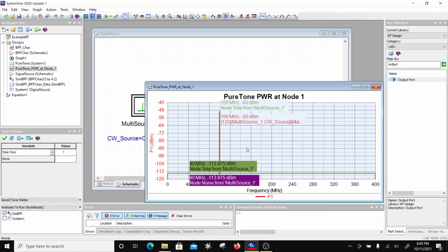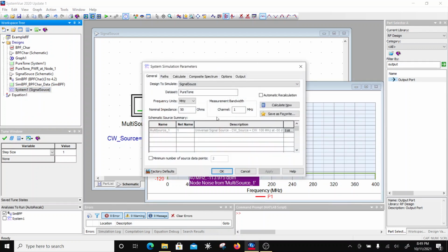So in case of the noise, in dB it will be 10 log 10 of 10 raised to 6, which will be 60. So if the noise floor is minus 174, then you add 60 to it. So minus 174 plus 60, that's going to be minus 114.